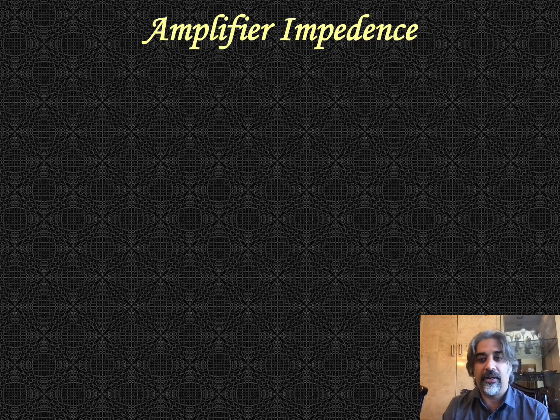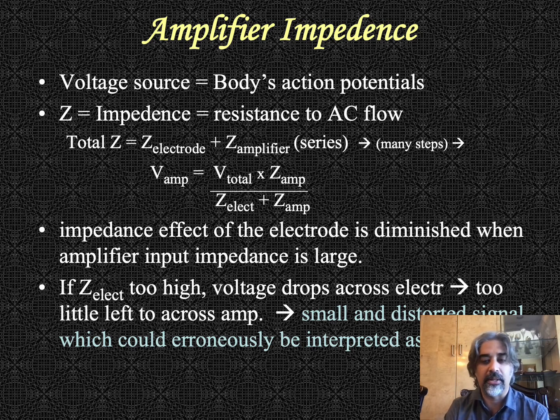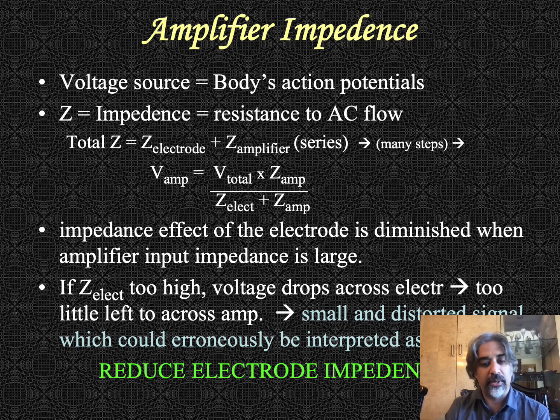The amplifier's resistance and capacitance are important parameters contributing to the amplifier impedance, and I am not going to go into this with you. But the point is to keep the electrode impedance low, if anyone asks.